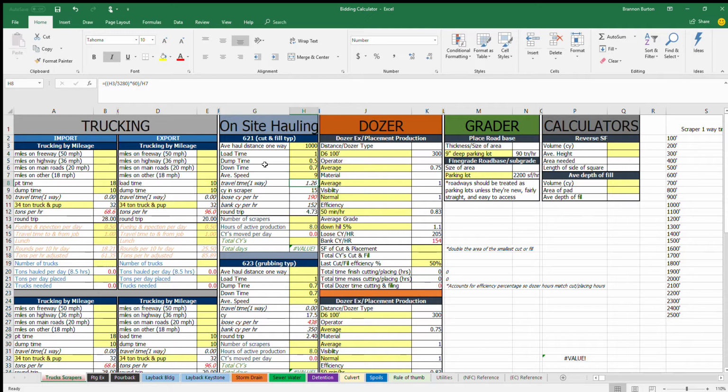The next number here is cubic yards in the scraper. I know the K can hold more material. We weighed the K, and the K can actually hold closer to 21. But from everything we've seen, the 21s are holding roughly 15 loose yards of material when they get pushed, on average. That's how much loose material gets in there.